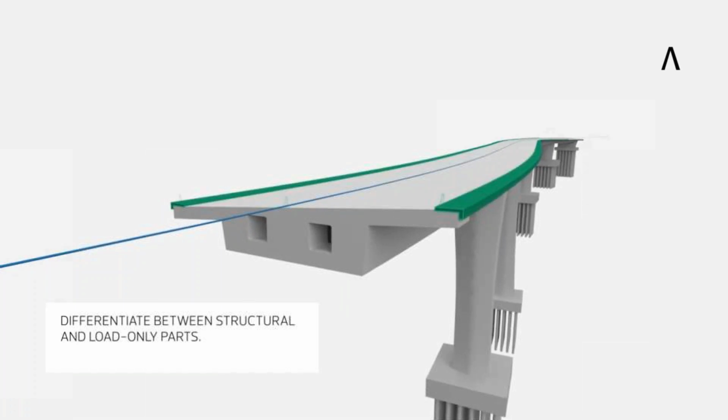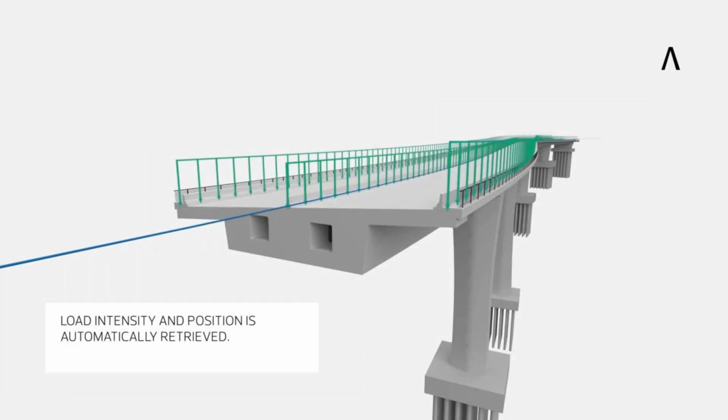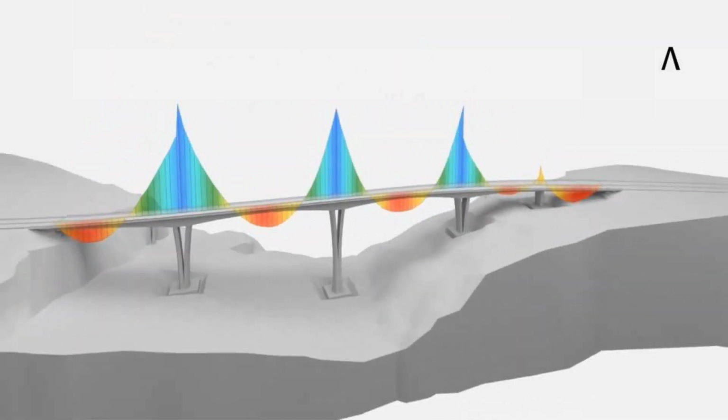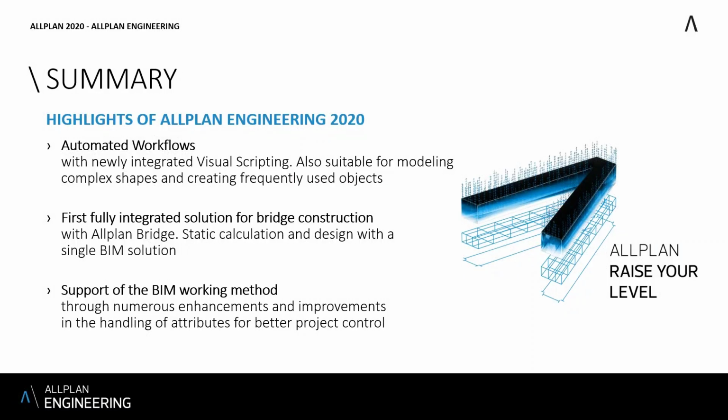And for structure, they're also doing structural analysis. So you can have the bearing part defined with some options, but apart from that, you can add some dead load items. So they are drawn, but don't have a structural role. They only provide some dead load. And then you get the forces distribution directly from Allplan. So you don't need to go to another software.